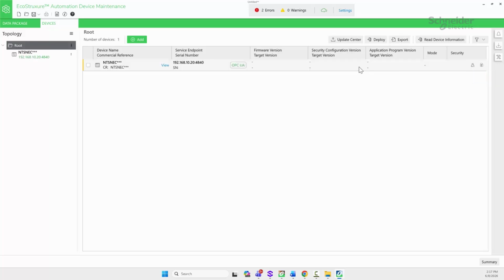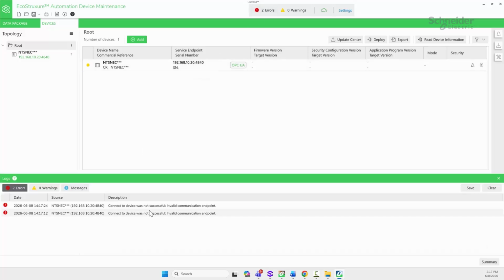Sometimes, if for some reason you can't connect and it's not working, you can also reset the user management. Sometimes it may not work the first time you try. This is where you would use the rotary switch on the back, set it to reset, and then apply power and basically reboot. This will delete the credentials and reset them to factory default.